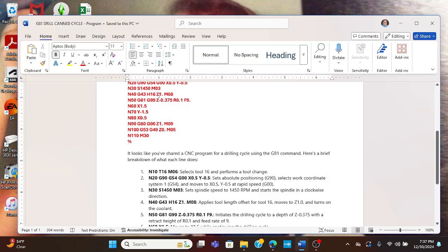And we're going to go 1 inch above the workpiece. That's what Z1 means. Okay, if you come down here, Z1 means you're 1 inch above the workpiece. Z0 is when the tip of the tool is touching the top of the workpiece. So a negative Z value would indicate that you're actually cutting into the material. Any positive Z value means that you're above that work plane. You're above the Z0 work plane.